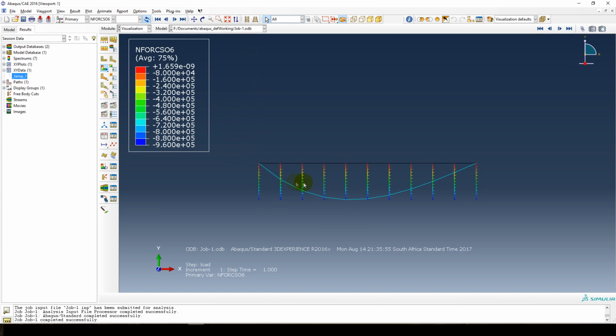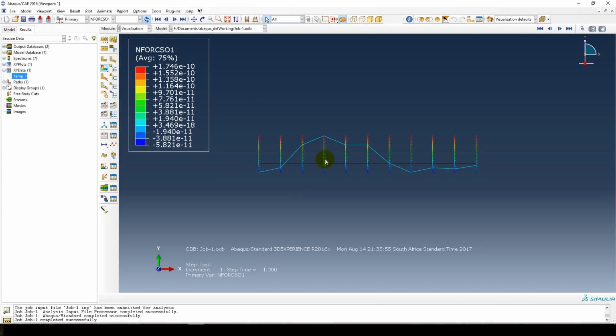for this loading condition. And it makes sense because our springs are pinned, or effectively pinned, so you have 0 moments at the ends and the moments distributed as such. Shear force, as such. Quite a nice representation, and axial forces none. Well, you can see it's effectively 0, it's just numerical discrepancies that cause the axial forces to do this. I mean, 10 times 10 to the minus 11 is effectively 0.